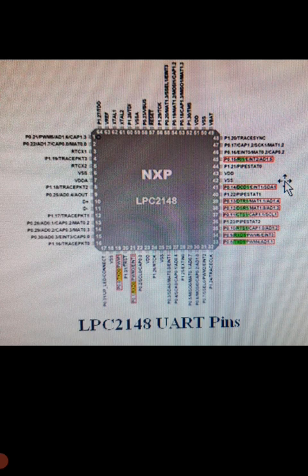The next pin is RI1, the input pin, the ring indicator signal pin. This pin is an active low signal which indicates that a telephone ringing signal has been detected by the modem. We will see how UART0 here and UART1 can be used in a similar way by the corresponding registers for UART1.